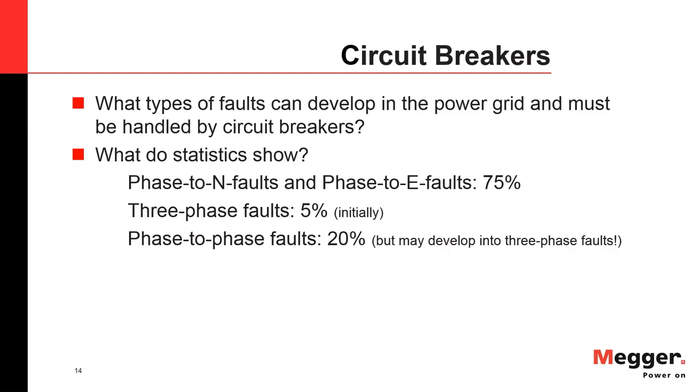Then you have these nasty three-phase faults, very rare but very destructive. And then you have the phase-to-phase faults, which are somewhere in between. But the problem with those is that they can develop into three-phase faults, and then you have the most destructive scenario again.